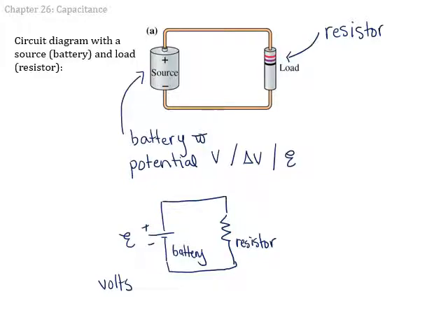When we hook up a battery to a closed circuit, we get a current flow. The direction of a current flow is from positive to negative. So the current flows out of the top end of the battery, the positive end. Of course, with what we know now about current, it is actually electrons that move around. It's the negative charge. But back when they defined current, they didn't know about electrons. So current got defined as the direction of the flow of a positive charge. And then that got fairly well entrenched into the books and nobody wanted to go back and change it.